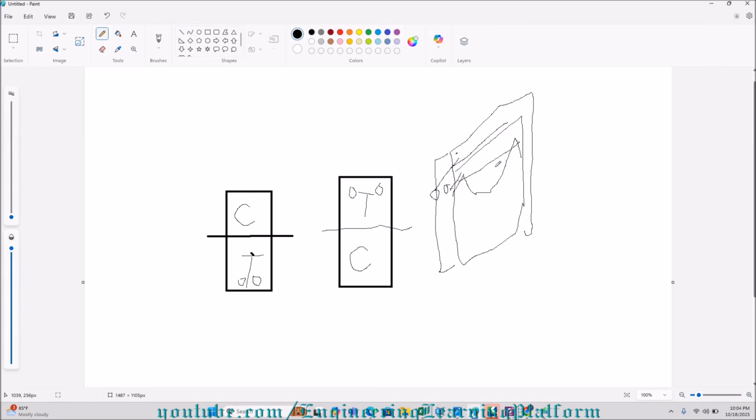in one case there is positive movement all along the beam, and in the other case there is negative movement. So negative movement means what? Your reinforcement should be placed at the top, it means it should be placed in the tension zone.